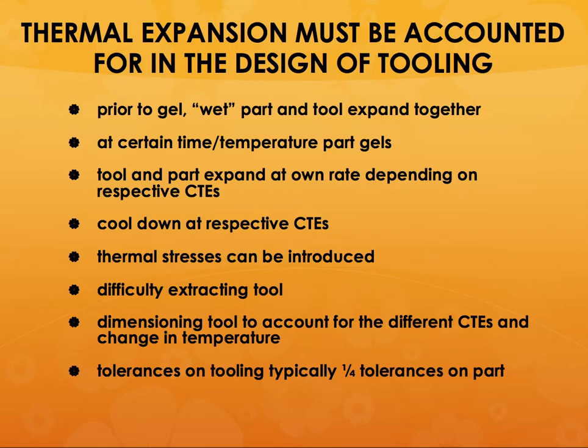So you may want to have a tooling that can be broken down, so you can just release the tooling. But that makes it extremely hard for you to make the tooling, extremely hard for you to design that into the tooling, and extremely hard for you to manufacture the part.